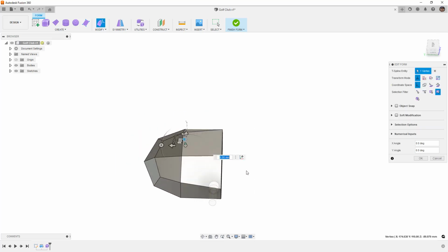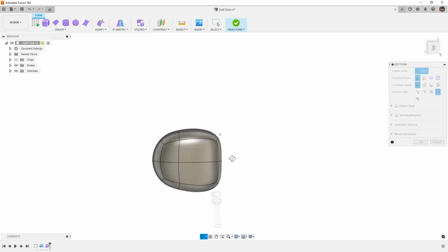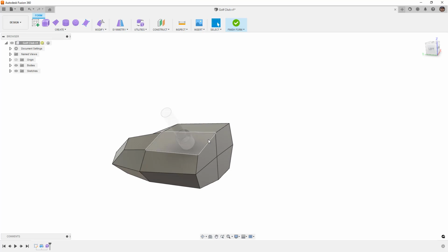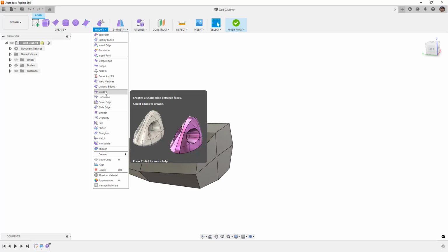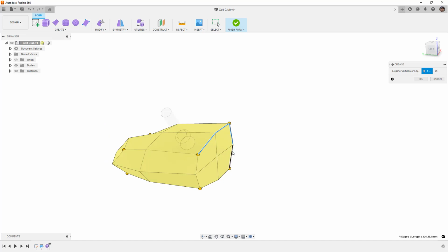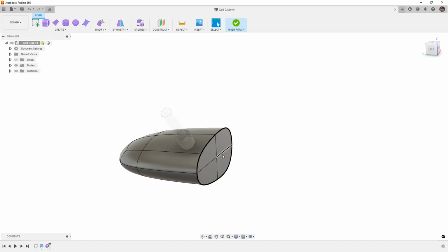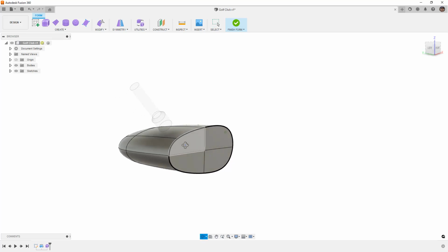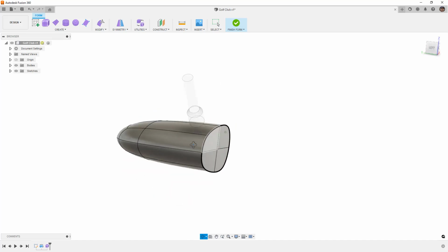So it looks okay. And again, I'm going to switch to smooth display just to take a quick look to see if we're in the right ballpark. Another thing you can do temporarily is take these front edges and crease them. Now, adding a crease, I did mention that this was one that was outside of the top 5, and this is not how I'm going to proceed. But if you crease it, it will give you that sharp edge, and then you can come back and add a fillet later. Now, the way that golf clubs are, the face doesn't just have a fillet on it. It has a fairly flat face, but then it will round out. So again, this is not the direction we're going. But if you like working in smooth display, you can add that crease, and that'll give you a little bit of an idea there.